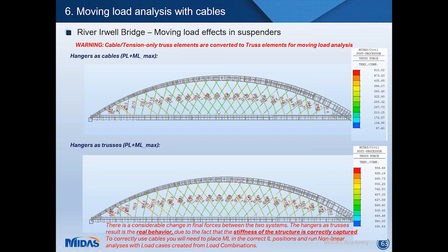Obviously, you can use cable elements and moving loads, but you need to use load cases created from load combination, because this is a non-linear model. So be careful when you use cables, because you're losing your superimposition effectively.